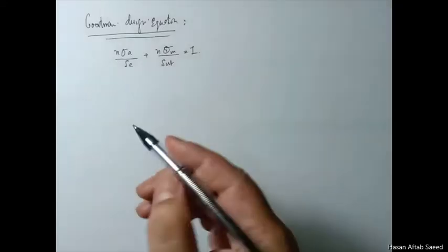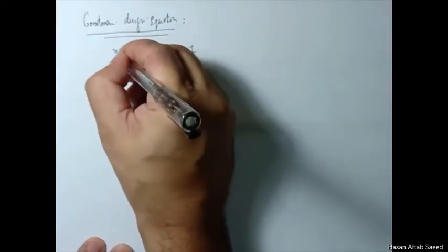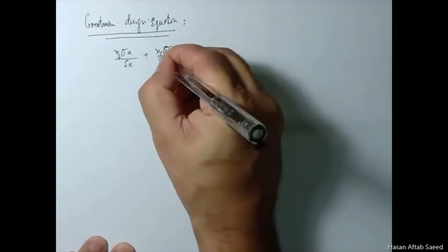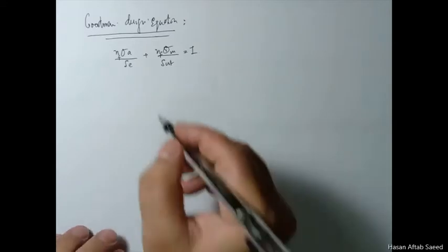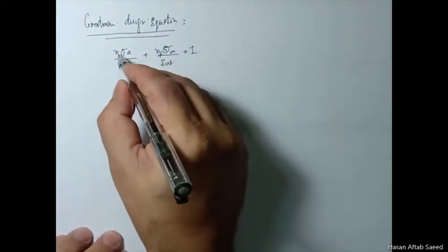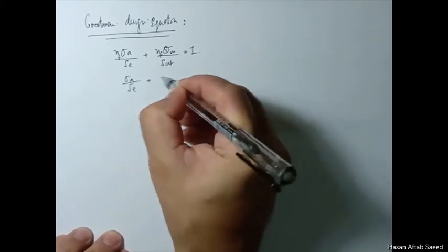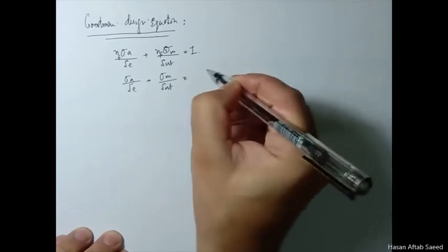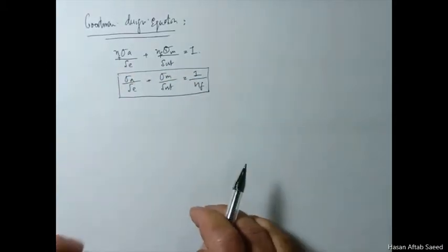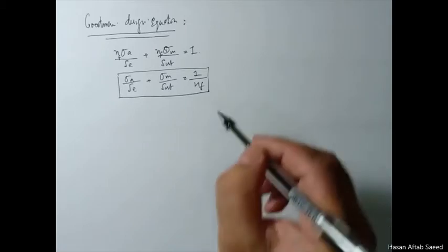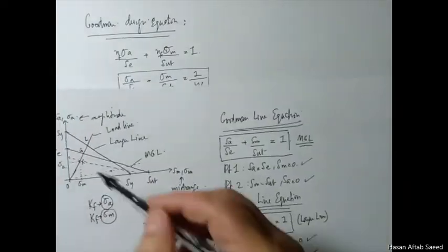Here I'll just use this subscript F for factor of safety, because we have two factors of safety, one for yield and one for fatigue. We are talking about fatigue here, so I use the subscript F, and if I rewrite this equation again, this is our design equation with factor of safety incorporated. The original equation was for this line.